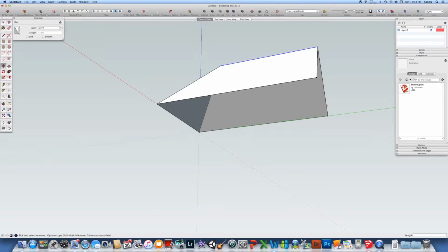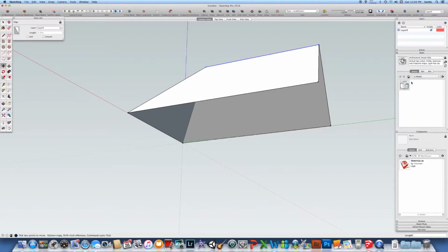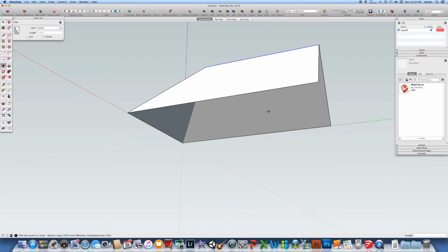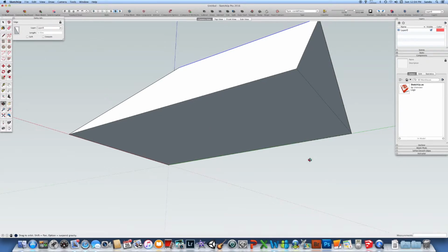And again, if you want to get rid of the end points, I said it in my previous video, you go to Style, you go to Edit, to the model type of style, and click on the endpoints, and that endpoint is gone. Therefore you have a clear view of where the endpoints are. Okay, so you can draw a rectangle again, and you complete your roof also on this side.